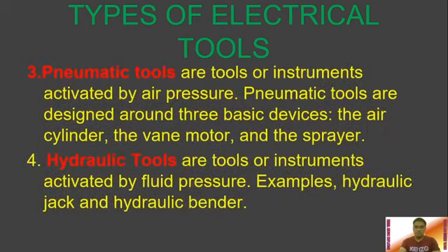Then we have the third type, which is pneumatic tools. These are tools or instruments activated by air pressure. Pneumatic tools are designed around three basic devices: the air cylinder, the vane motor, and the sprayer. Pneumatic tools are any tools that are activated by air pressure, where the air is coming from a compressor. That's why we have the three basic devices that comprise pneumatic tools.